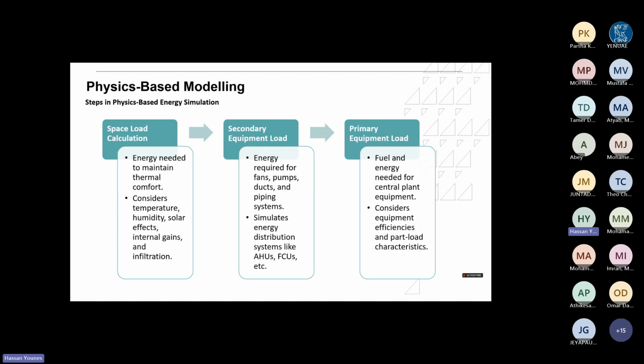So I would ask for different outdoor temperatures for an air-cooled chiller, for different load factors on the chiller, and typically the supply temperature from the chiller itself would be constant throughout the year, unless you're increasing the temperature during winter. Then you need to also ask for that map at different supply chilled water temperatures from the chiller itself. So you need to be as accurate as possible. You need to put in as accurate information as will be used at that site.